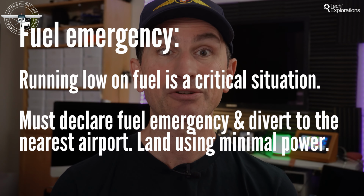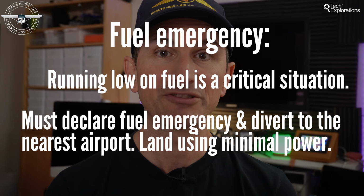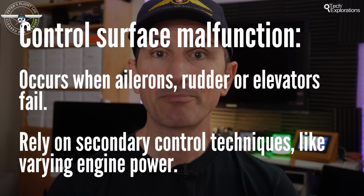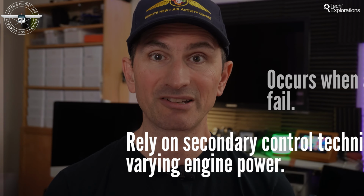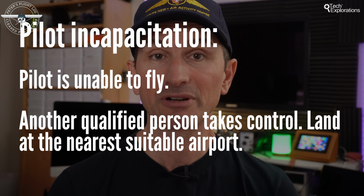Fuel emergency. Running low on fuel is a critical situation. The pilot must declare a fuel emergency and divert to the nearest suitable airport. Landing is executed using minimal power to conserve remaining fuel. Control surface malfunction. This occurs when the ailerons, rudder, or elevators fail. To maneuver the aircraft, the pilot must rely on secondary control techniques such as varying engine power. Pilot incapacitation. If a pilot becomes incapacitated, another qualified person may need to take control of the aircraft. Immediate landing at the nearest suitable airport is the general procedure.